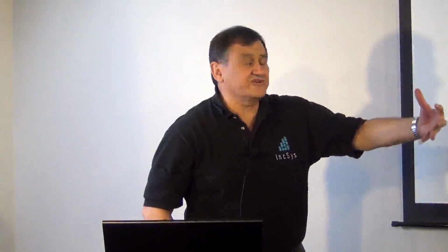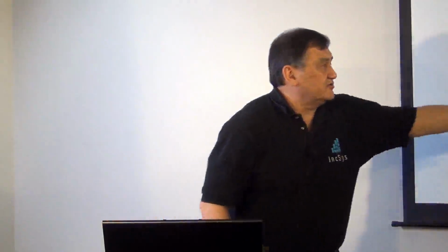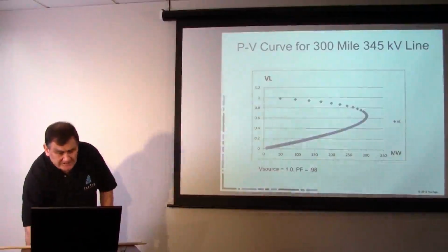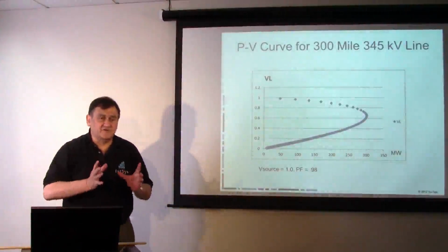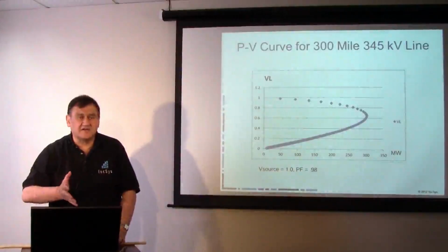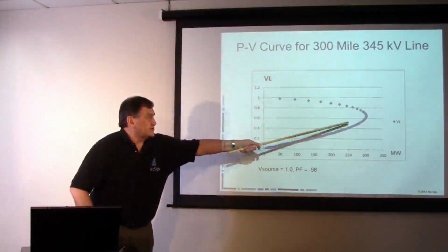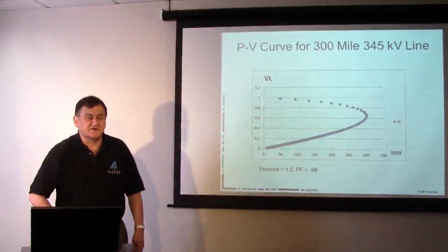You've got to understand where you have radial transmission systems. You may start out with having generation support at this end. That generator is going to tend to hold the voltage up. But if that generator hits its megavar limit, you get back into this characteristic and the voltage collapse occurs. We will get into this in a lot more detail, but I just wanted to have a preview before we get into the characteristics of the initial device, of all the different types of devices. This is the fundamental underlying characteristic of radial systems, and this causes voltage collapse.